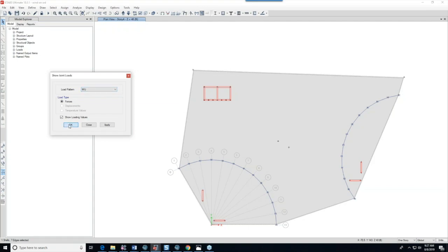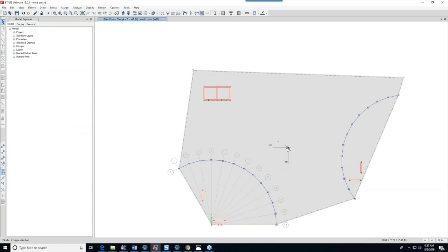And if I say show the wind load, well, if they're user assigned wind loads, the program wants to assign these things to a single point, but there is no joint nearby. And so the program is going to look for the closest joint to assign these loads. And I have some internal meshing on this slab, but it's going to look for an externally meshed joint to assign these loads. You have to be a little cautious about that.